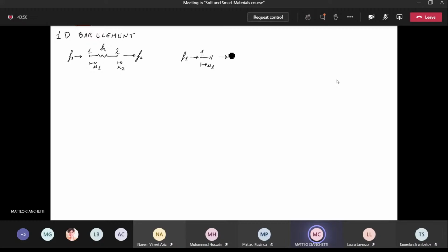and then there is the force that connects the two parts related to node 1 and node 2. The force that I'm considering here, of course, is the force related to the spring, the stiffness K that I used for the element. For us, F is given by Hooke's law, which defines the internal force.